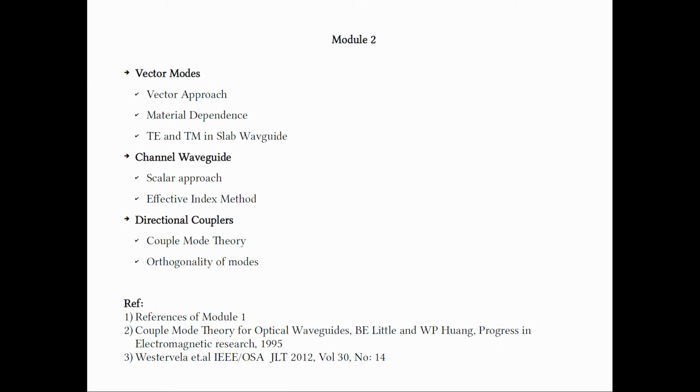So, after substituting the superposition into the scalar wave equation, we obtained a set of differential equations for A and B, which are called the coupling equations. The coefficients of the coupling equations are K_ij, which consist of all the parameters of the structure, like the spacing between the waveguides, the waveguide design, the refractive index contrast, the operating wavelength, and so on and so forth. In particular, the spacing is a very sensitive element. As you increase the spacing, the coupling reduces and more length is needed to couple the waveguides.